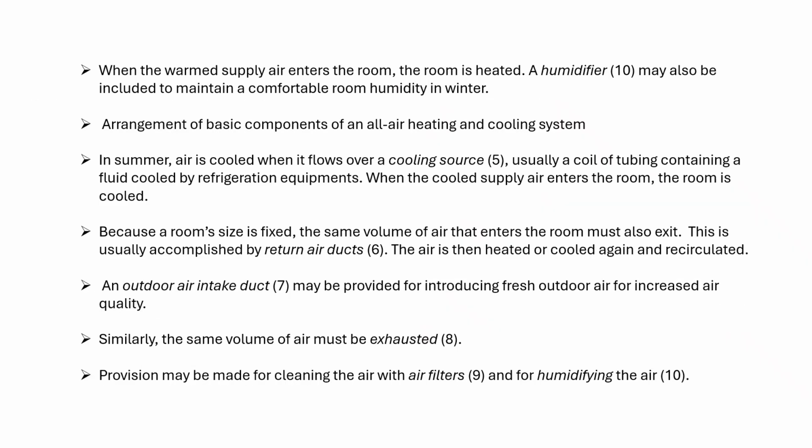So when the warmed supply air enters the room, the room gets heated. The humidifier shown in the figure may also be included to maintain a comfortable room humidity in winter. So they are maintaining a comfortable humidity in the room. So during the winter season, the arrangement of basic components for an all air heating or cooling system has been shown, and how the structure works.